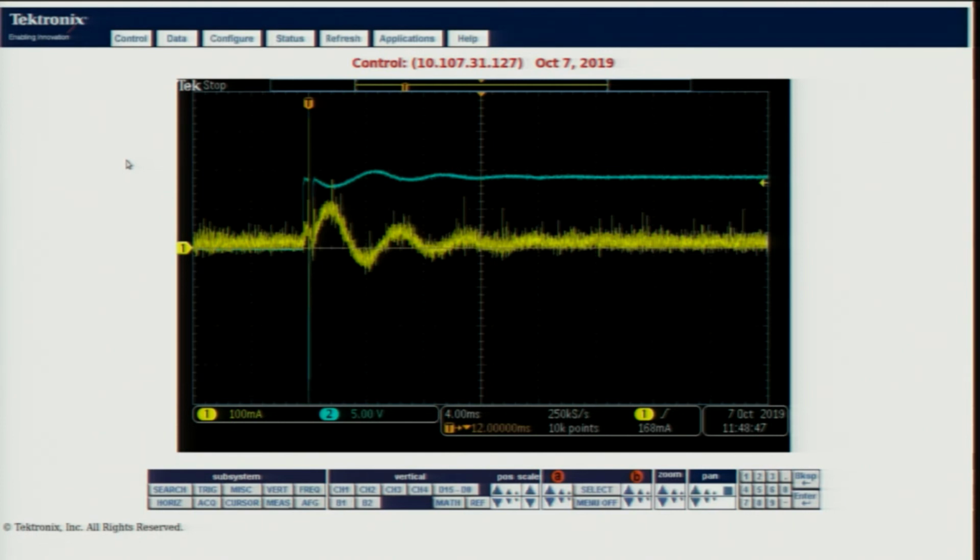You are likely to get some deviation. The reason is of course that the resistance of the winding has not been considered here. In the theoretical analysis we consider 10 ohm, but here the resistance will be slightly more than that, and therefore you will find that the natural frequency will not match exactly. So, this is one interesting thing.